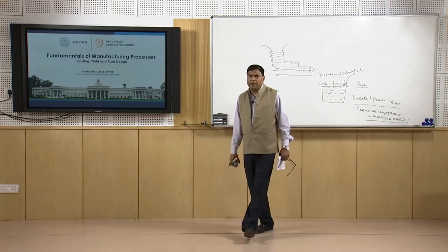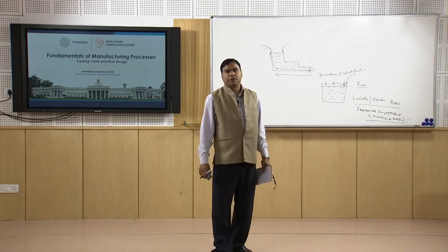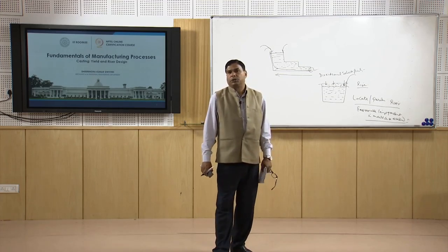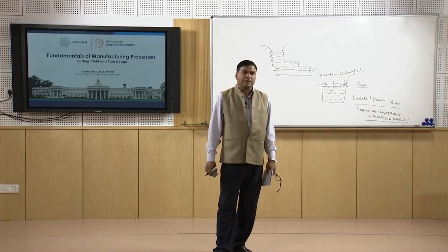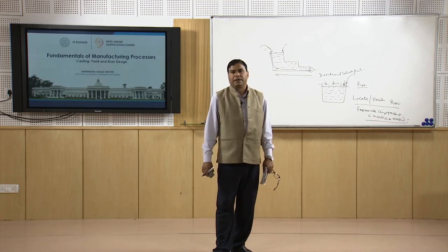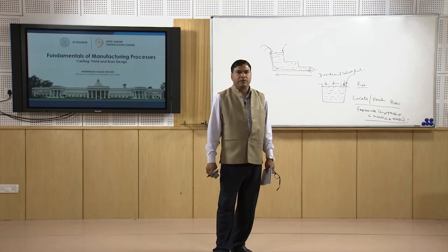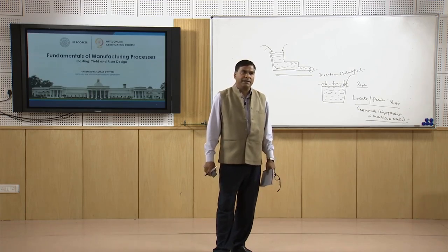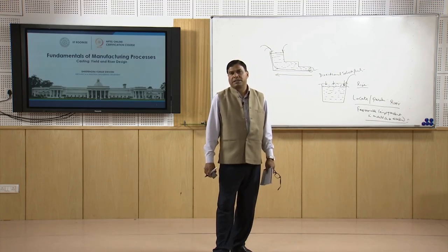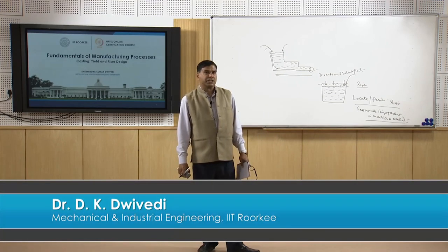So, now here I will summarize this presentation. In this presentation, I have talked about the casting yield, which shows the economics of the foundry industry, and also how solidification takes place in castings, and how we can regulate the solidification pattern in castings in order to avoid hot spot formation in the interior zone of the castings, which would eventually lead to shrinkage cavities.